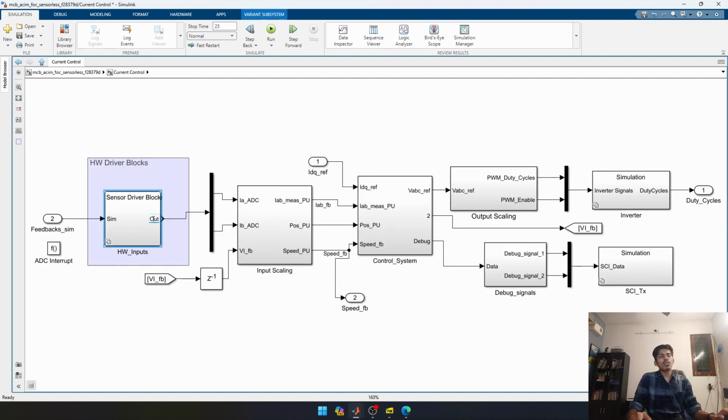So now we get the current either through the actual hardware ADC or through the virtual Simulink induction motor model. Either way we get the current. We get two currents, IA and IB; we are muxing the two currents inside, and here we are demuxing them through IA ADC and IB ADC. So we are receiving it from that.